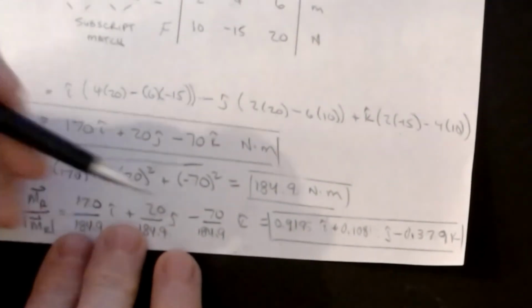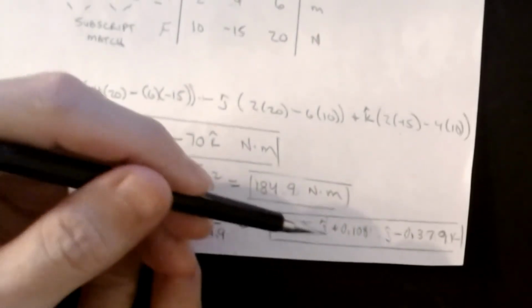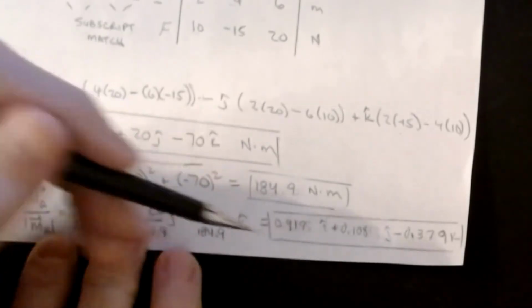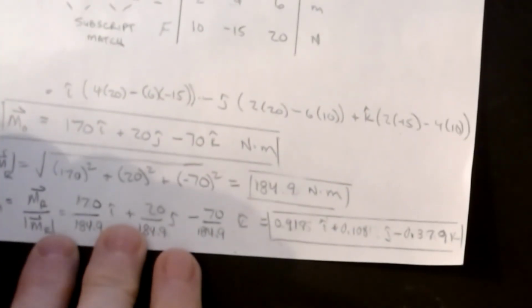All right, so if you wanted to test this to verify, and this is always a good idea, I didn't do it in this example, but you could check. The one thing you want to make sure of is that if I square these coefficients, sum them, and take the square root, this should come out to be about 1.0. Now it won't be exactly 1, just because of the round-off errors, but it should be something like 0.999 or 1.001. It should be very, very close to 1 to indicate that this is indeed a true unit vector coming out of our calculation.